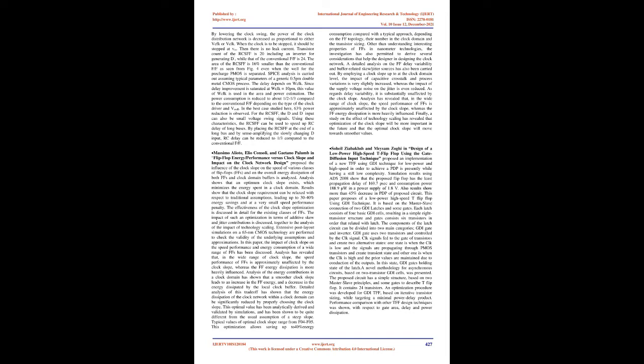Pei Zhao, Tarek K. Darwish and Magdi Bayoumi, in high-performance and low-power conditional discharge flip-flop, analyzed high-performance flip-flops and classified them into 2 categories, the conditional precharge and the conditional capture technologies. This classification is based on how to prevent or reduce the redundant internal switching activities. A new flip-flop is introduced, the conditional discharge flip-flop, CDFF. It is based on a new technology, known as the conditional discharge technology.